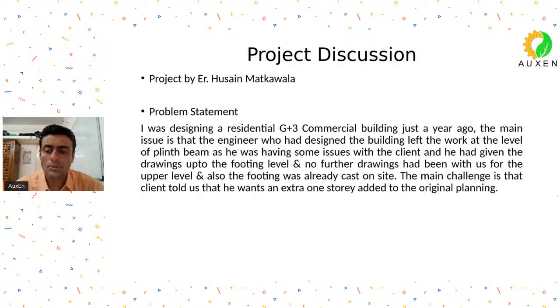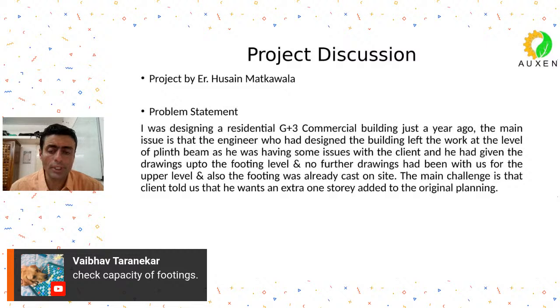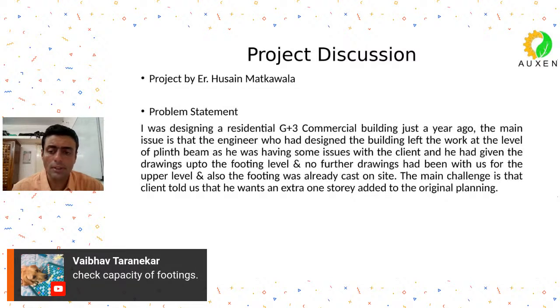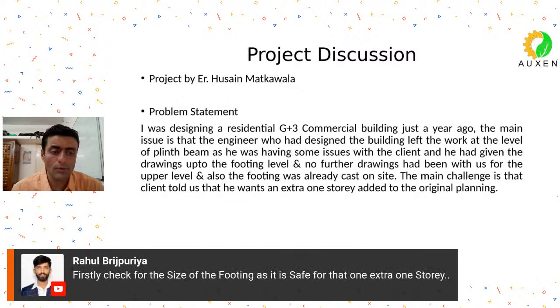Yes. So Mr. Weber says check the capacity of footings, but that will come later. First, initially you will have to prepare, let us say, some model, and then, so how can you start? Of course, you can start by preparing some computer analysis model, and then in the analysis model you can add that extra story. You can then apply all the possible loadings, isn't it? You can apply all the possible loadings, do the analysis, and then check the main things that you need to check, which, of course, would be the foundations, because the footings have already been cast. So the footings need to be properly checked.